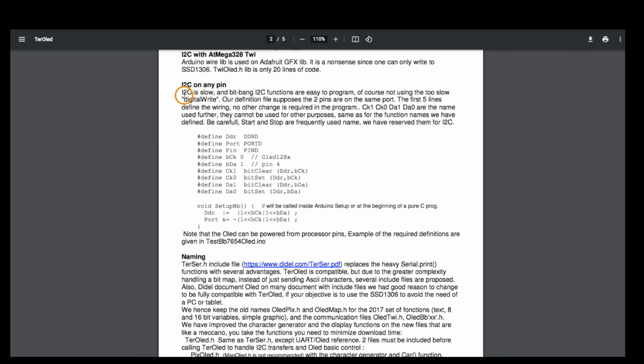And what they're doing for I2C is bit banging it, so I can keep the ATtiny's dedicated hardware I2C pins for talking to that other Uno, but I wanted to keep the OLED on its own dedicated software-controlled I2C bus. So to do the bit banging, I found I had to go in and change some of these things because the ATtiny 0 series doesn't refer to ports and pins the same as classic Arduinos.